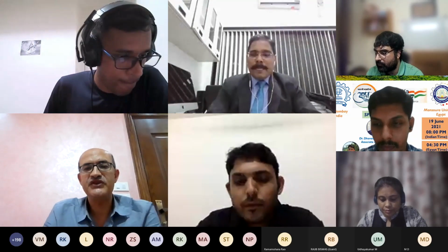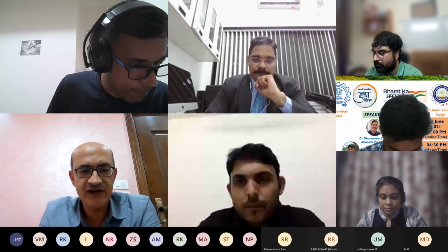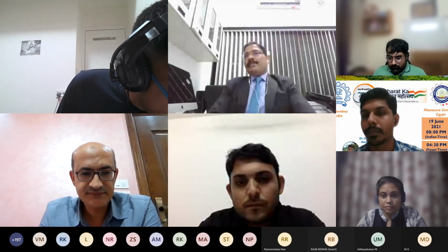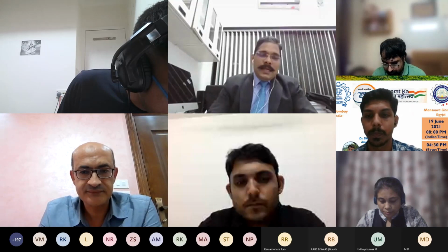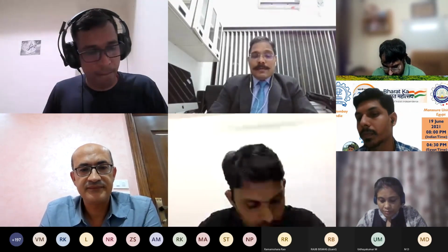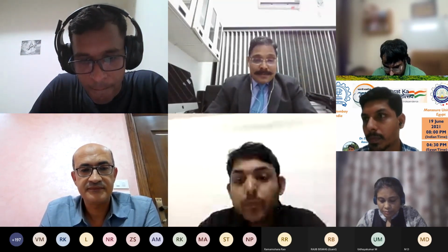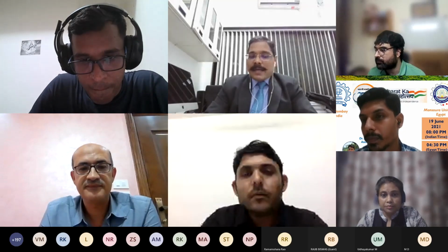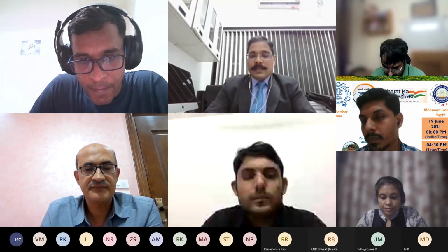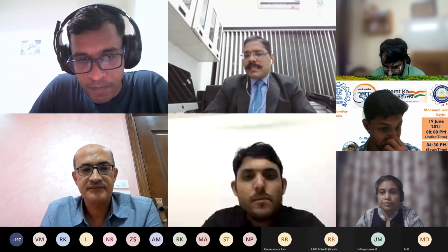Professor, did you hear about any problems during construction of these highly modified binders in the field? Professor Sarif, I think this is a very good question. In fact, there was a concern that if you use very highly modified binder like PG82, that binder might be very stiff. And we have seen there is a practice also of using warm mix additive sometimes in the highly polymer modified binders.